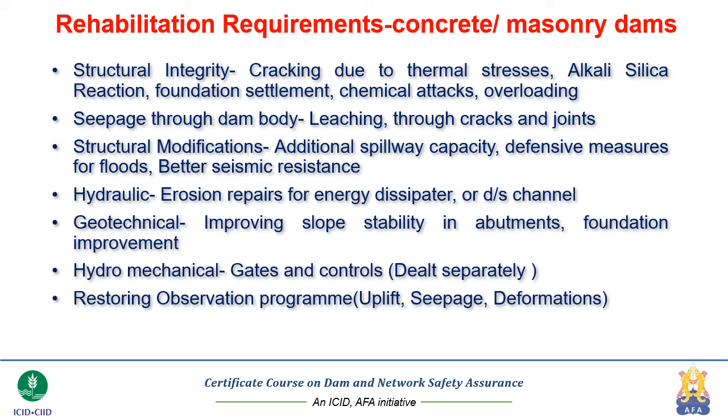Restoring the observation program is also equally important, and this should become a part of the rehabilitation requirements, wherein at least for the concrete and masonry dams, even if we may not be able to provide or replace the embedded instrumentation, the uplift, seepage and deformations, these three are key observation requirements which have to be set up, and for which mechanical and topographical survey specialized equipment is available. Seepage measurements are relatively simple and can be implemented quite quickly, but these observation programs will also need rehabilitation.